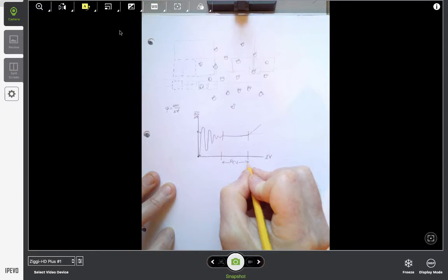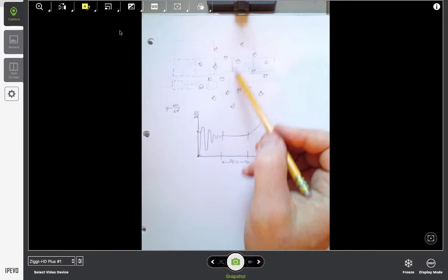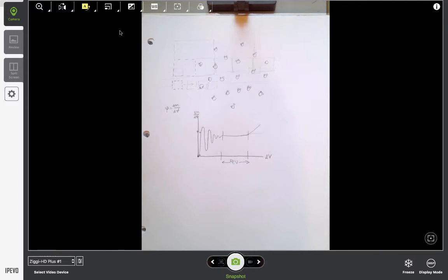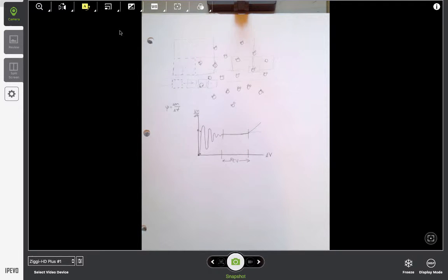is called the region of the representative elementary volume. So when you come across the word representative elementary volume, all the author means is that whatever sample size we're using is big enough to get multiple molecules every time if we're sampling in the fluid, and the result is approximately constant for that particular material. So the usual definition would be that the mass density can be defined, and it's assumed to be controlled by the sampling volume. The lowest usable volume, a sampling volume, is called the representative elementary volume. And when this is true, when we're in this region, many of the principles of continuum mechanics of the book are adequate to describe fluid behavior.